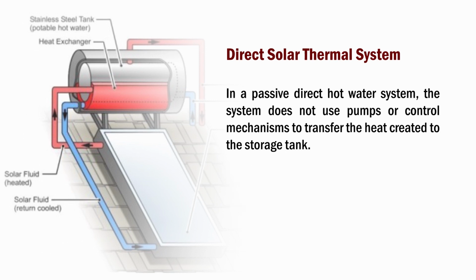It is a passive direct hot water system. The system does not use a pump or a control mechanism to transfer the heat created to the storage tank. Instead, passive systems are what are called open loop systems, which use the natural force of gravity to help circulate the water around the system.